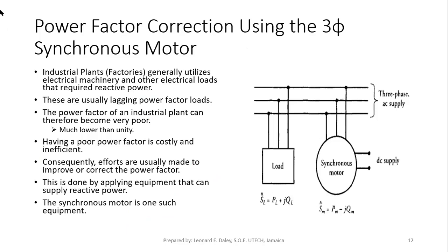All right, so normally factories utilize a lot of electrical machinery, mostly induction motors and other loads that require reactive power. Now, these are usually lagging power factor loads, and hence the power factor for our industrial plant can become very poor, much lower than unity. Now, having a low power factor